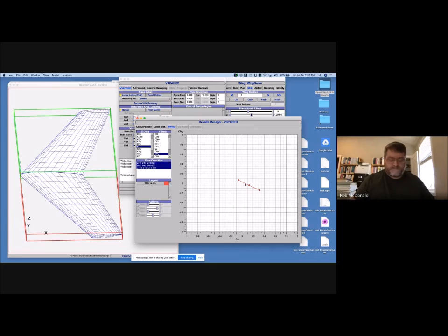And so what that means is there's an expression when you learn to fly, which is pitch for speed, right? When you talk about your airplane, when you're at high angle of attack, you're at high CL, and in order for the airplane to trim, for that to work out, you have to be flying slow. Okay, and when you go to low angle of attack, you're at lower CL, and in order for the airplane to trim, you have to be flying fast.